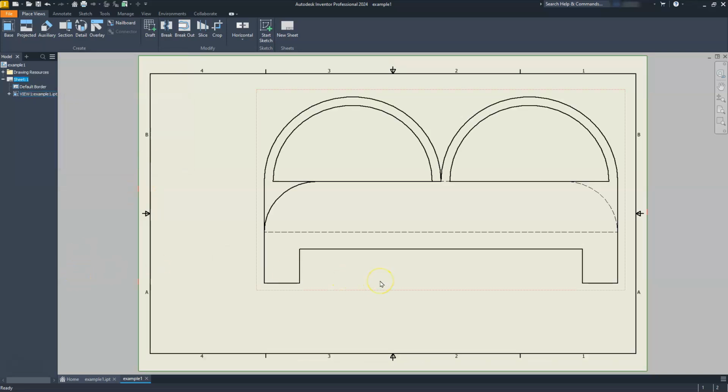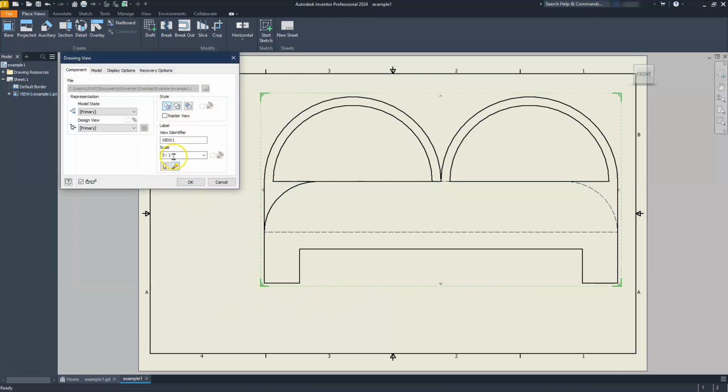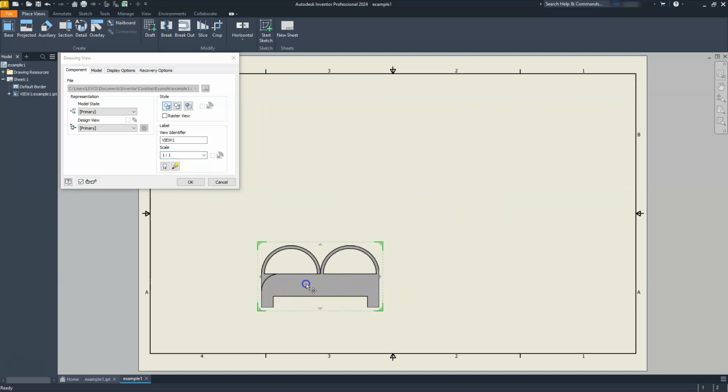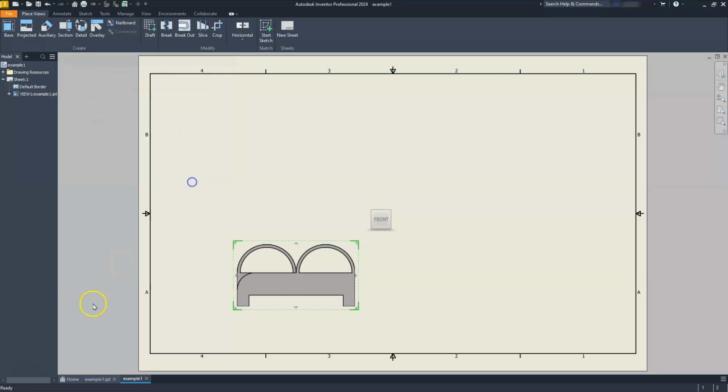You're going to see that now this 3:1 is super big compared to the other one. So don't get caught up on what size title block it is and things of that nature. The principles are going to all act the same. It's going to be the scale that's going to drive your drawing no matter what. So whatever size you typically use, the process will still be exactly the same. So in our case, if I use this as a B size, I need to scale this down, right? So I need to bring it back down to maybe 1:1 or some of that nature.